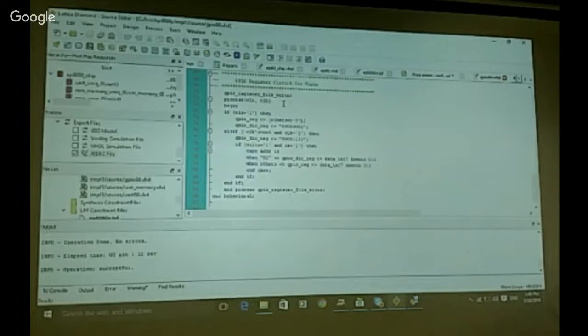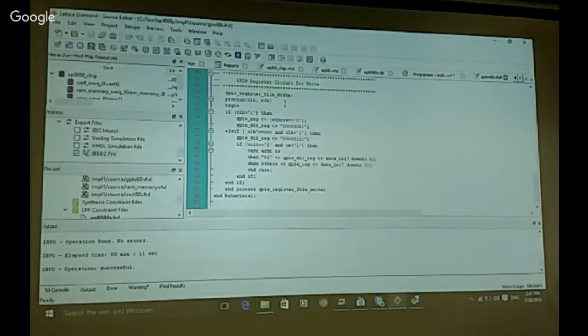Additional setting for the baud rate. Beside the baud rate, parity set to none. This page, set to none. No parity. Okay, got it. And anything else? Let me see. The stop bit 1, data bit, parity none, and hardware none. It seems to be okay when I open the ports.